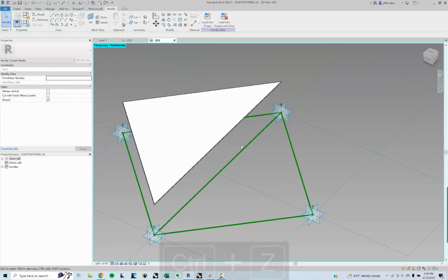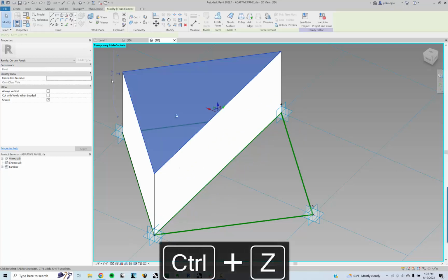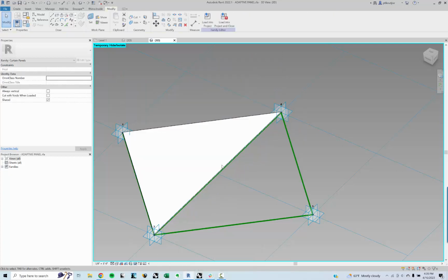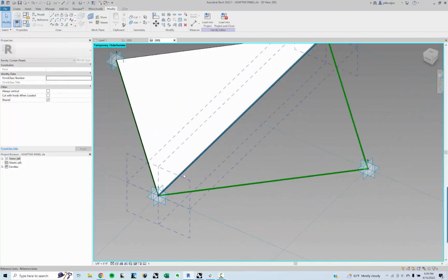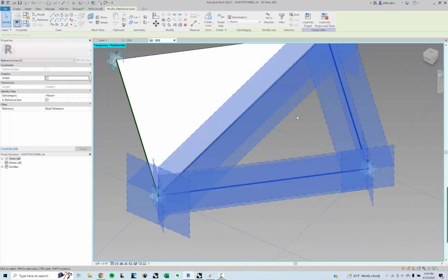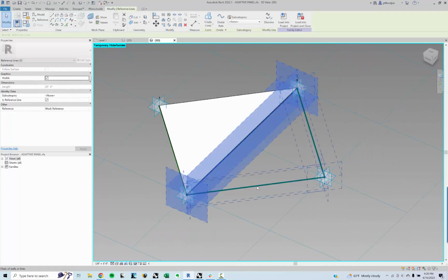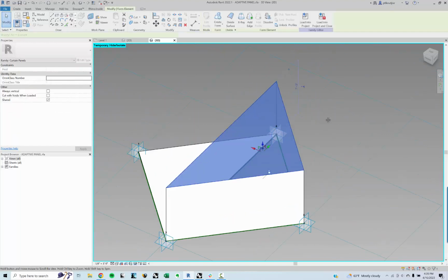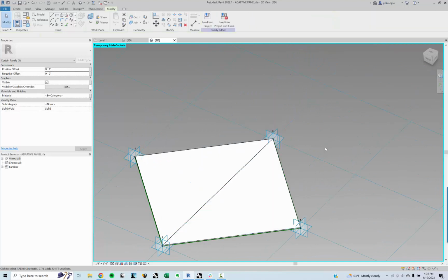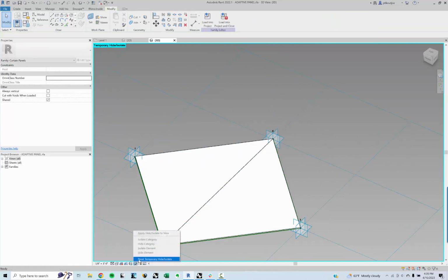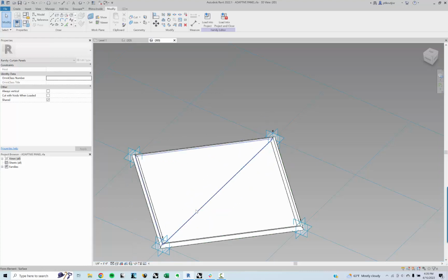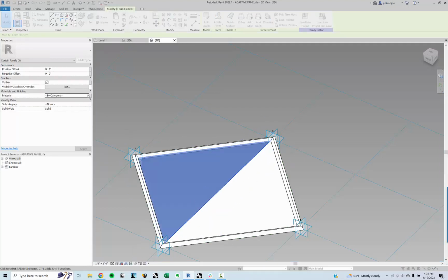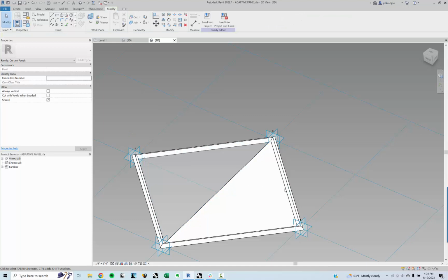That's not what I want to do. Let me click on this surface, click 1 inch. There we go. So you want to click on the surface that you want to move. And now I'm going to grab the same thing here, this, and this, and do create form, and then pick this top surface, make this 1 inch, and now I have this triangulated panel. I can reset my temporary hide to isolate, make this material glass, make this material glass over here.